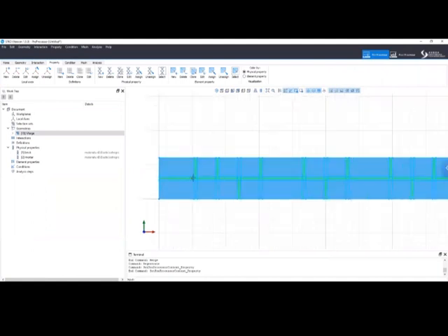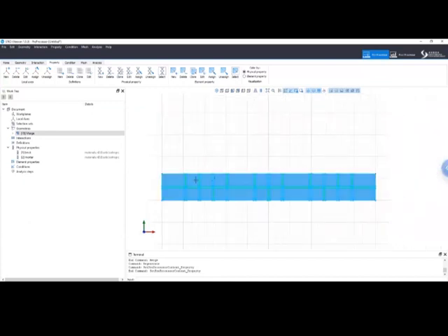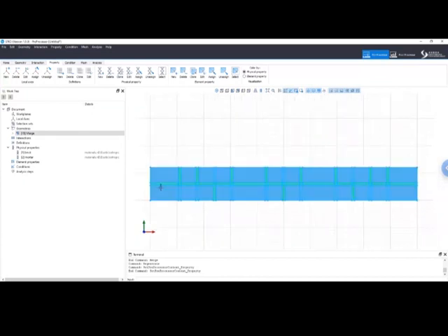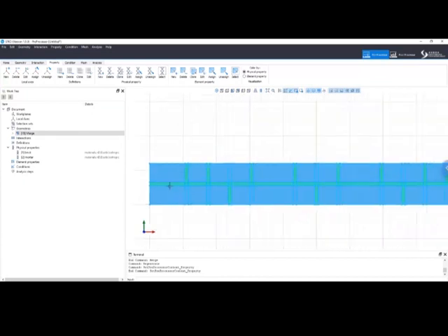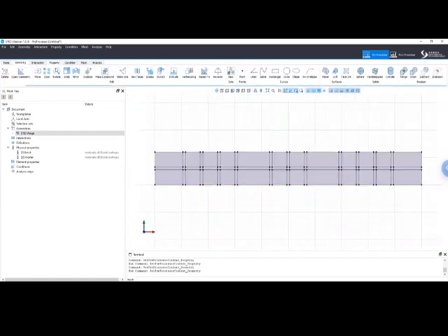We just need to copy this face down so that we have a module that can be repeated. Okay. So let me copy this surface, or actually instead of copying it, I can use another geometry command that I will show you, which is the extrusion, and I can click on extrude. Now the extrude command can extrude everything.